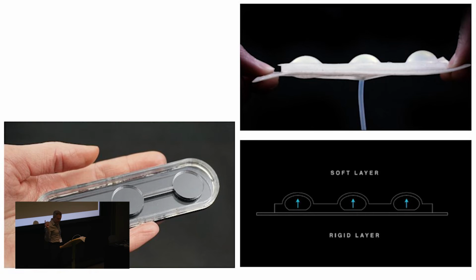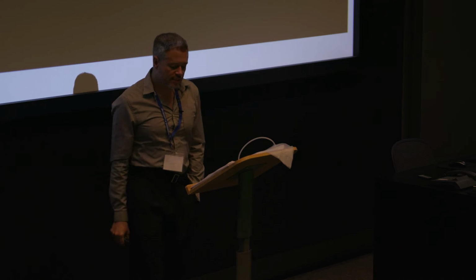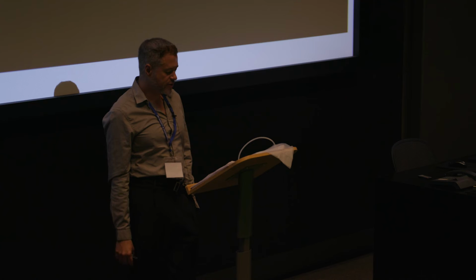So next, we experiment with the silicone mold technique. For this actuator, we built the mold using the laser cut technique, which is a piece of acrylic that you cut and separate, then glue together to make this mold. After the mold was assembled, it was time to use the silicone.